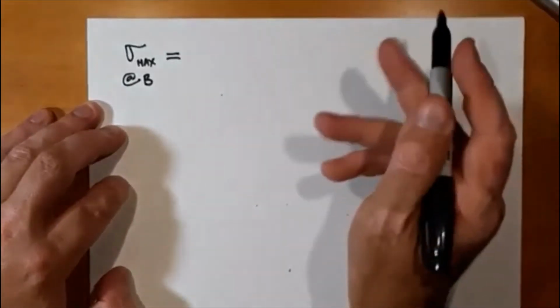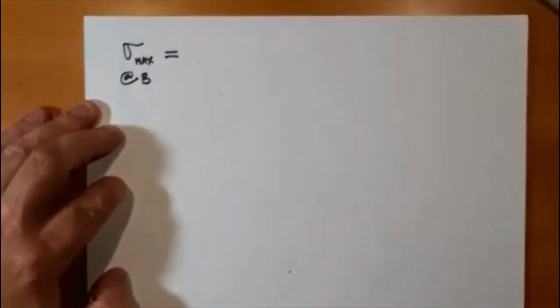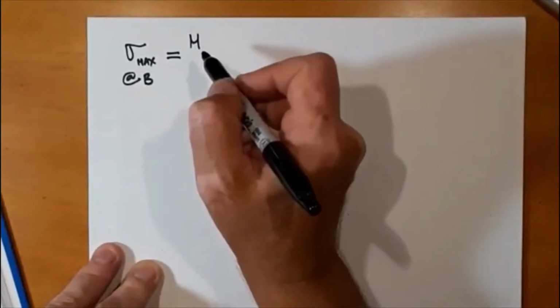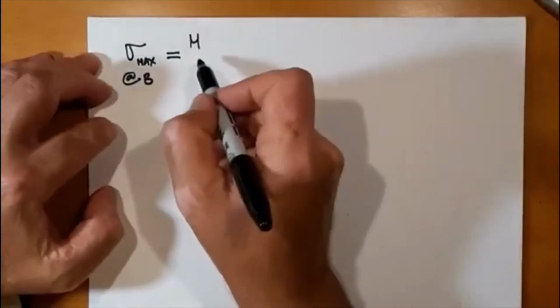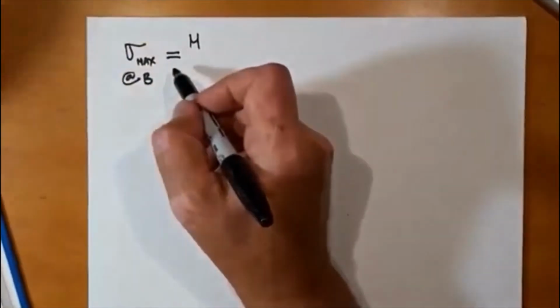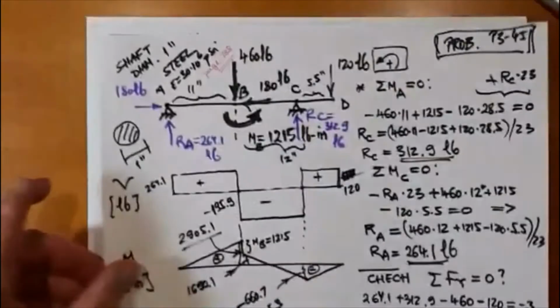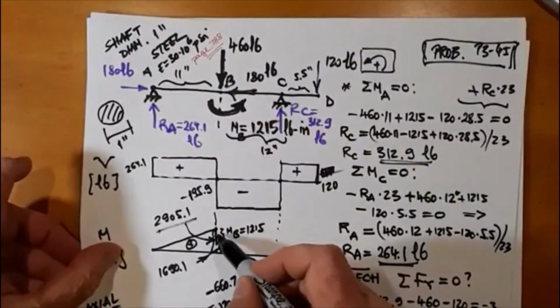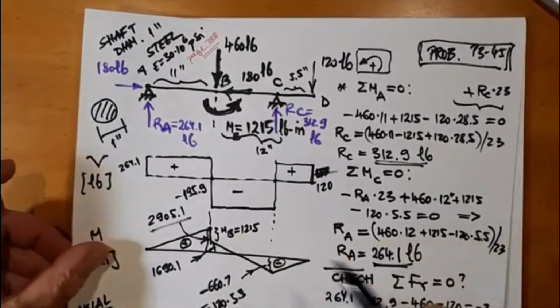And remember, tensile stresses are worse than compressive stresses, so I'm going to use the M. It will be M at a maximum at point B, but not MB the way I had it. Okay, so MB is the external moment at B, although here we're talking about the maximum moment on the diagram.